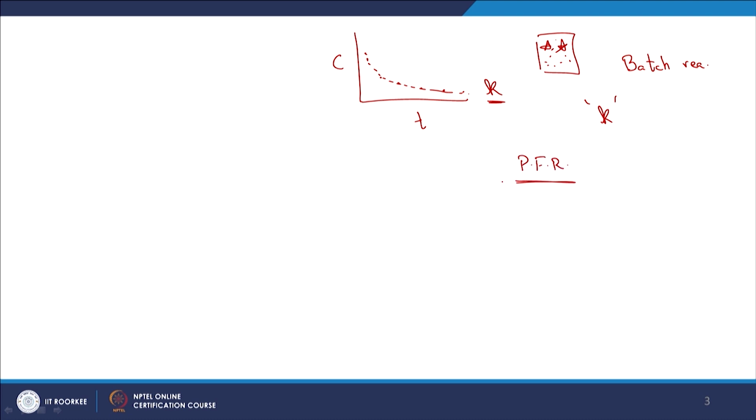So, one aspect that needs to be kept in mind is that we have our rate of loss equal to rate constant times A, where A is area per volume, right, area of zero valent iron per volume of water, times the concentration of compound, right. So, here I am using the K that I am measuring in the lab, right, but typically what K am I measuring? I am measuring the pseudo first order rate constant, it is not the true rate constant, because I am going to put in a lot of zero valent iron, let us say, or a stoichiometric excess of zero valent iron.